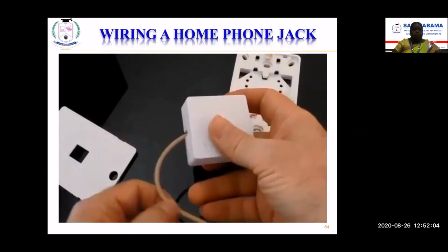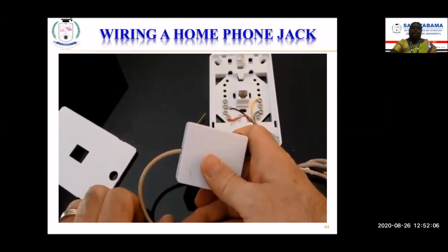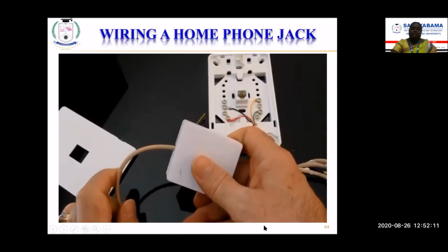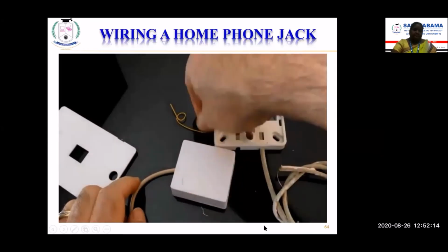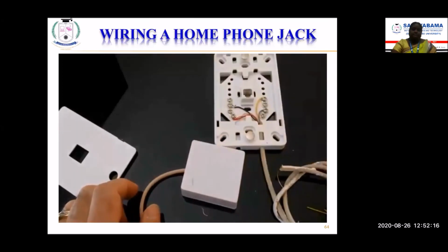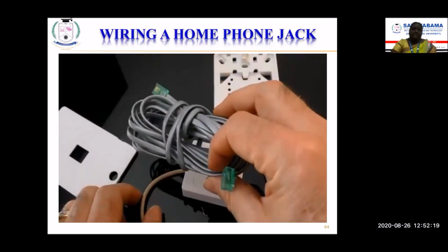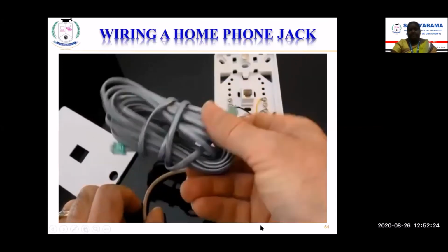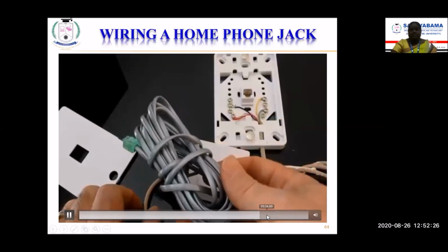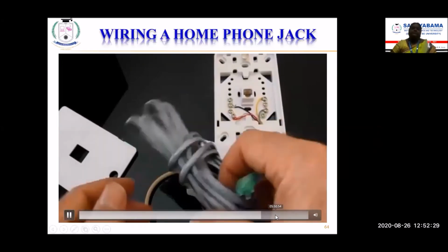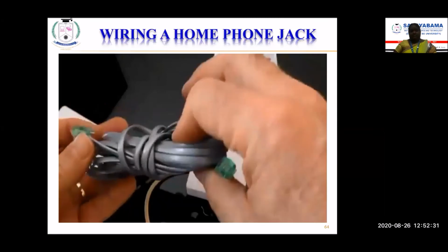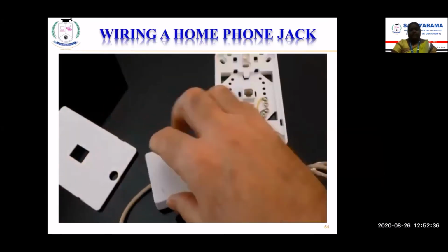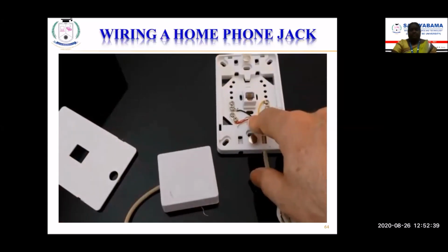Now, if you need some more of this wire, you can get it at most hardware stores. It's referred to as household phone wire or just phone wire. However, what you do not want to use, and I absolutely cringe when I see this, is don't take one of these, what we call line cords, and cut the end off and try to use those wires inside. You're just asking for trouble. It doesn't work well. Can you make it work? Yeah, maybe, but it's not a good practice, and it usually causes more problems than it's worth. Get real phone wire. All right, same idea applies to wall mount and also to surface.